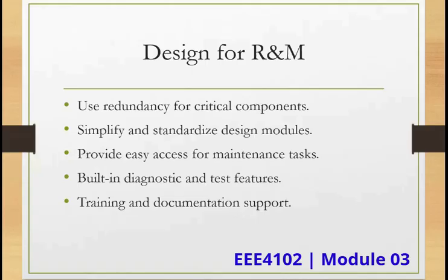This is why many industrial controllers usually have plug and play modules, whereby if a module is faulty and needs to be replaced, you just remove it and replace it with another one. So that design is more simplified for someone to easily maintain. So making the MTBF low, and doing so availability goes high because it takes less for you to maintain.